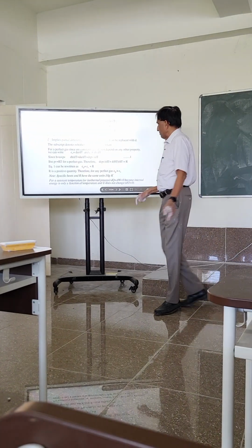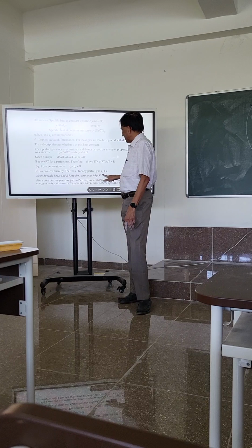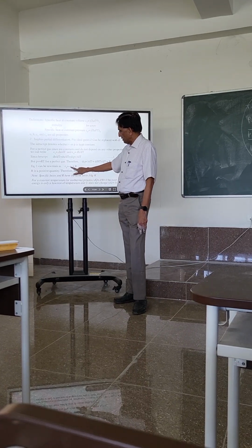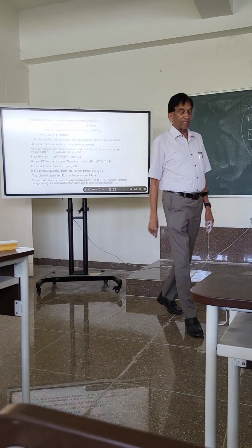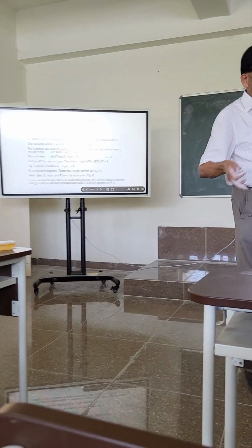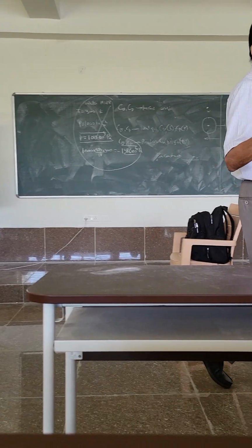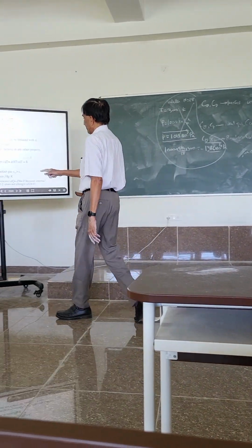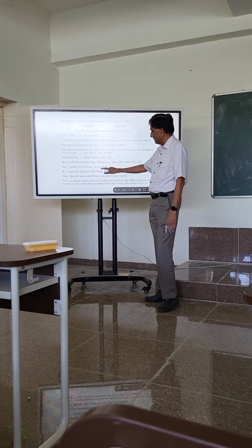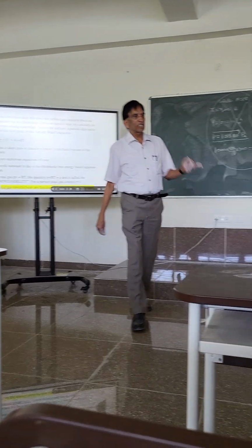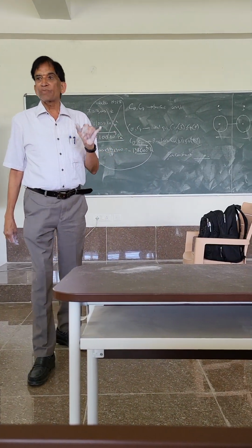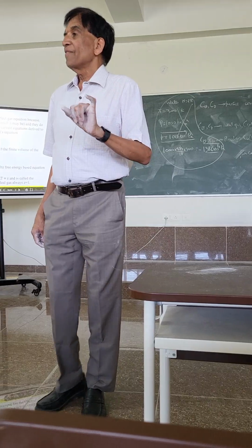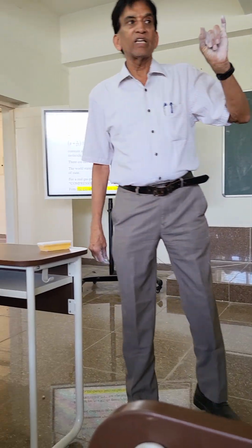Now again, let us see one more thing. Cp is always greater than Cv. Why? Cv is some number, and R is the gas constant, depending upon mole or mass basis. It is always a positive number, not negative. So when you add a positive number to any given number, the result has got to be greater than that number. So another thing that we got to learn is that the specific heat at constant pressure will always be greater than the specific heat at constant volume.